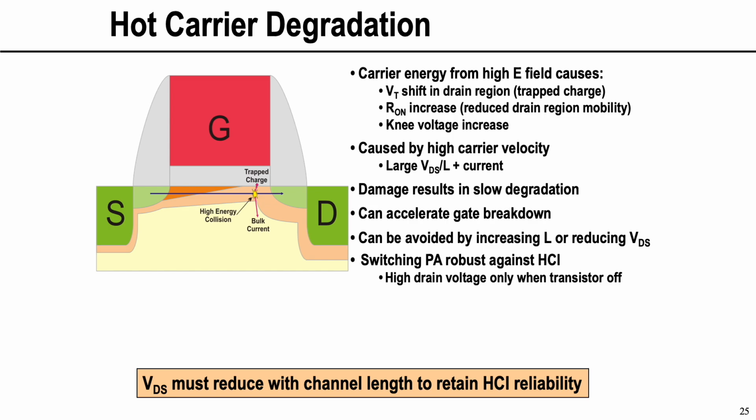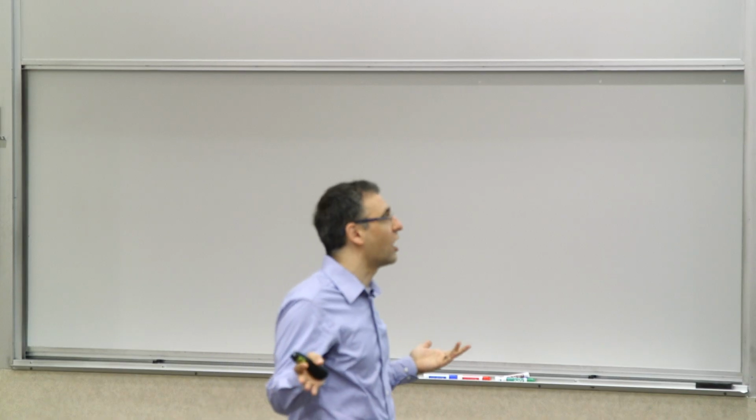In a state-of-the-art transistor, you can imagine that if you apply too much of a voltage difference between this gate and the drain, then at that point you can have a breakdown. If there's a current flowing, all of a sudden you can cause catastrophic, irreversible damage. Basically, at some point your voltage exceeds something, charge passes through, current passes, damages the oxide, and the transistor is done.